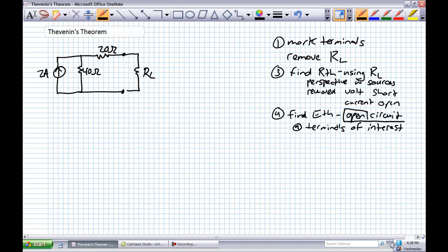So before you start doing the calculations of those dozen different load resistors for that particular circuit, my advice to you is stop. Don't do it. Take a breather, do the Thevenin's equivalent of the circuit, and then calculate the IL, VL, and PL for those dozen different resistors. Okay? So stop, don't do it.